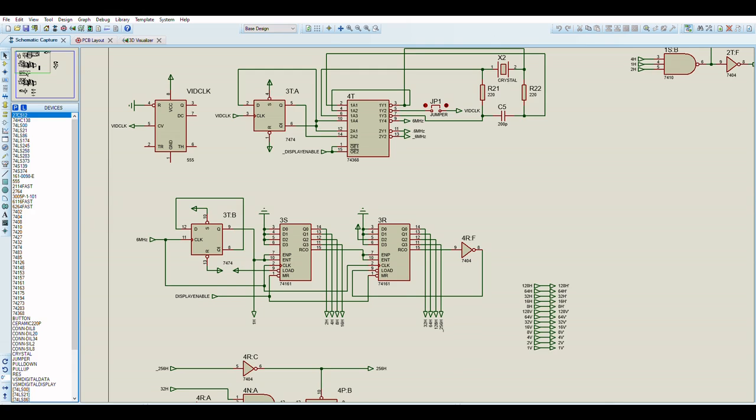It's also used to trigger the start of the scan line logic for rendering sprites. For example, it's used to trigger when tile data should start to be read, should start to be processed. So basically we have a pixel being output on every tick of a 6 megahertz clock.